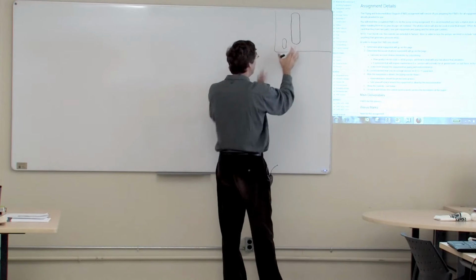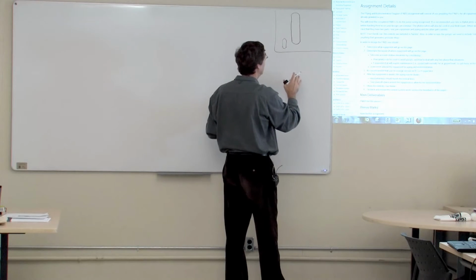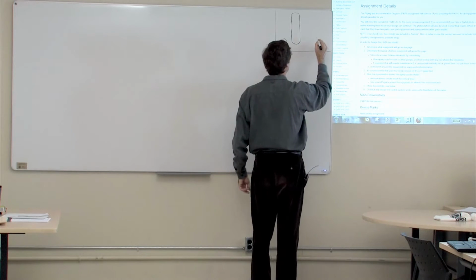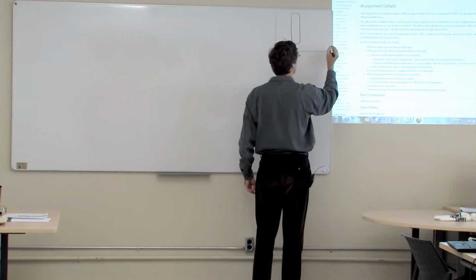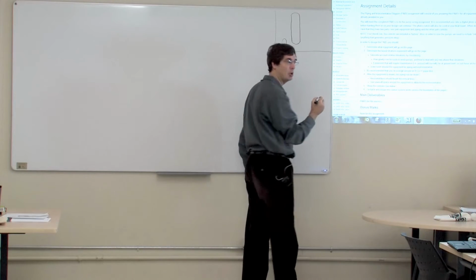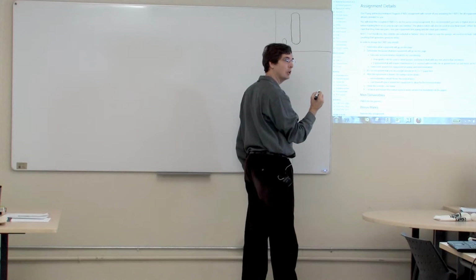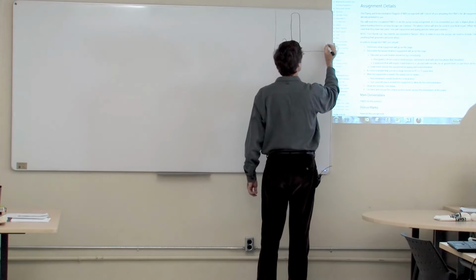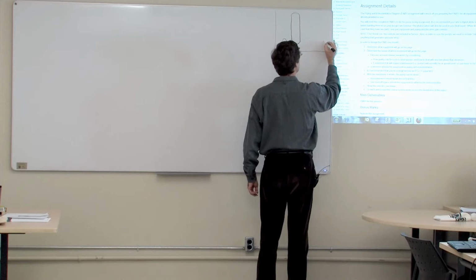Okay, so I think I'm going to put my reboiler kind of here. I know I've got to get a product cooler in, and I think most people were coming up with small product cooler sizes, so you're probably using double pipe heat exchangers. So I'm going to put a small double pipe heat exchanger roughly about here.